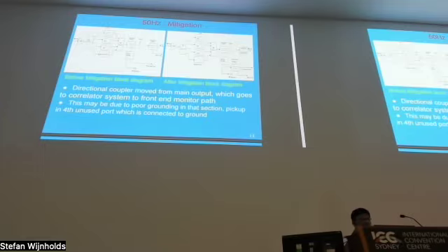So we suspected this directional coupler. We moved this directional coupler to the other part of the circuit where the same signal was used for front panel monitoring purposes. So there we moved the directional coupler to that path. With this, the 50 Hertz got reduced drastically. This 50 Hertz was maybe due to poor grounding of the port.